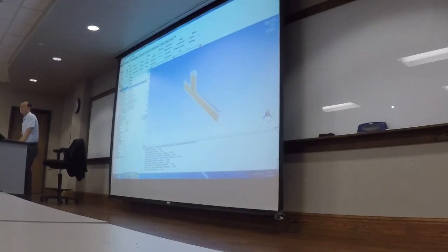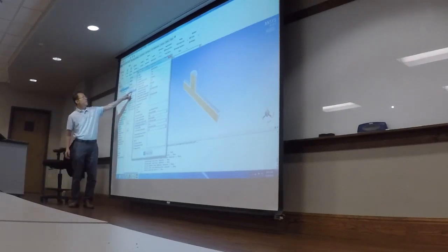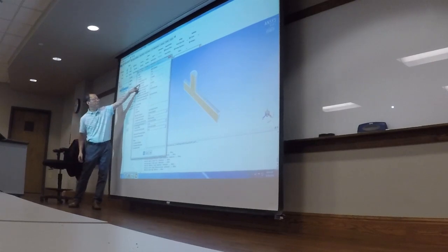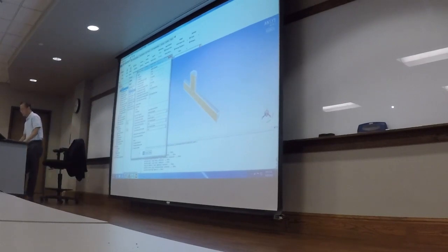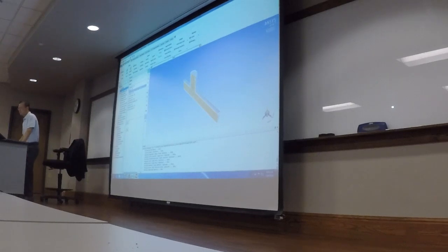This time, we only do fluid flow. There's no heat transfer, so let's not turn on the energy equation. Let's leave it off. Viscous flow, k-epsilon, let's do the same, enhanced wall treatment. So for viscous flow, instead of laminar, we're going to do turbulent, k-epsilon model, enhanced wall treatment, everything else default. All right, that's it for models.